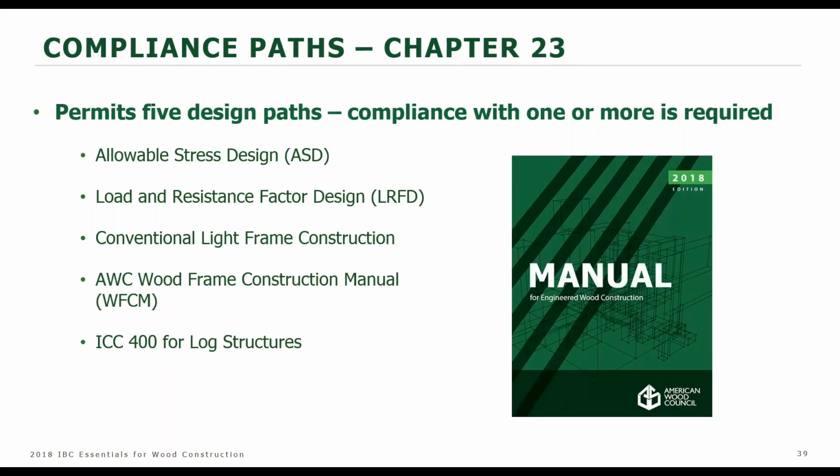The IBC itself gives you some alternatives for design. Allowable stress design is most often used for wood. However, load and resistance factor design, our manuals, our standards, the NDS, as well as the IBC and so forth, are set up so that you can use LRFD, the LRFD design methodology. It is fairly easily converted in the NDS.